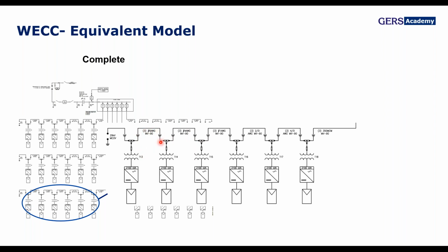For example, here you have a 6 AWG for the first inverter, but at the end of that feeder you will have a 350 MCM. So depending on the power that flows on each section, you'll have a different conductor.